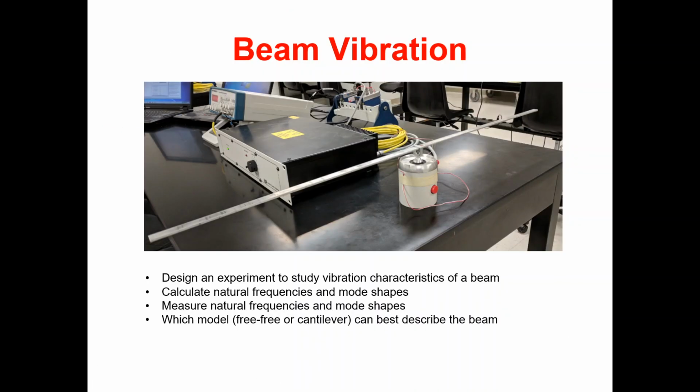Okay, but as mentioned before, what we are going to talk about, and this is the beam you're going to see in the lab, is the beam vibration. We are going to design an experiment to study the vibration characteristics of a beam. We want to calculate the natural frequencies and mode shapes. We want to measure the natural frequencies and mode shapes. And we want to determine which model, free or cantilever, can best describe the beam.